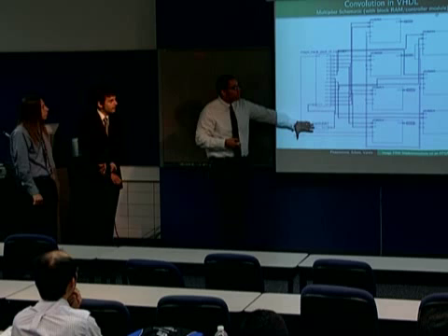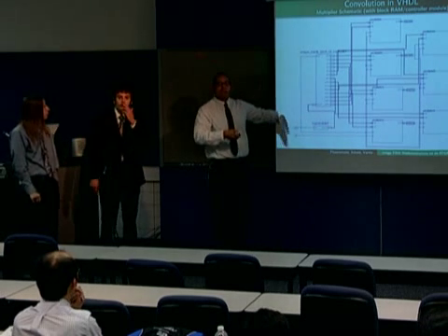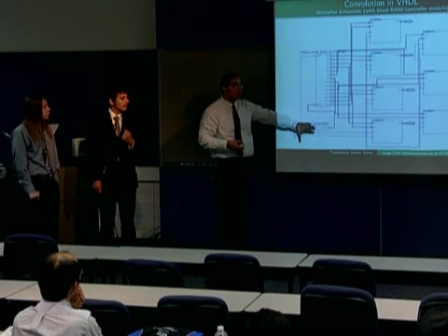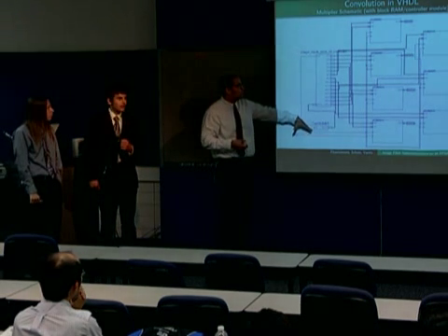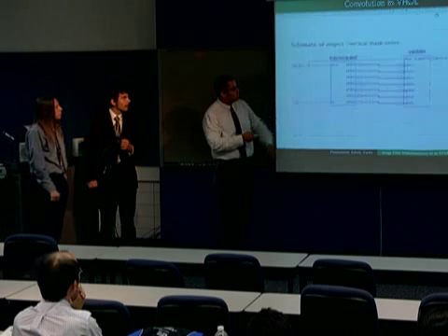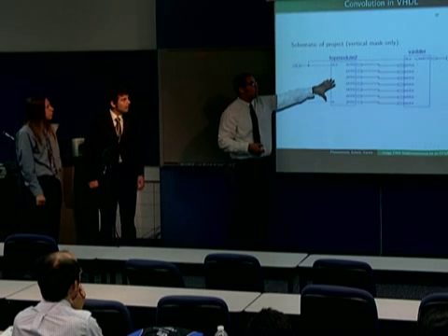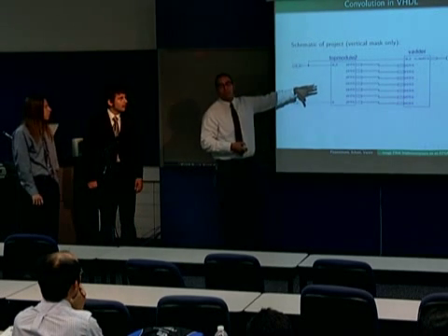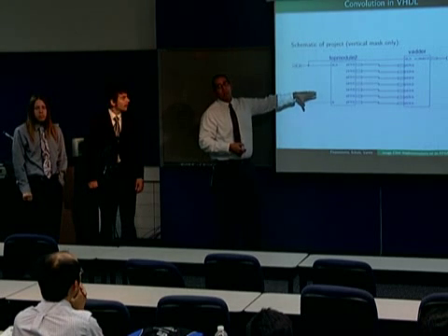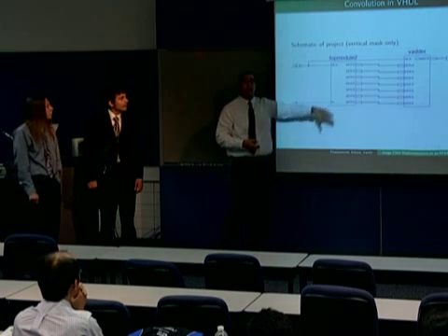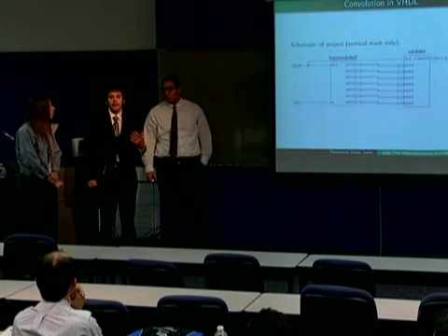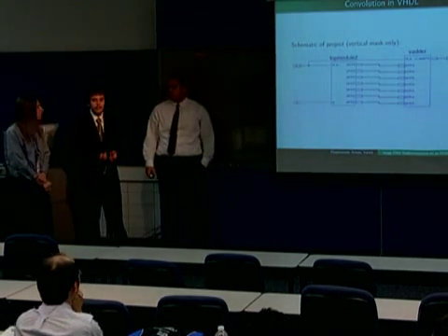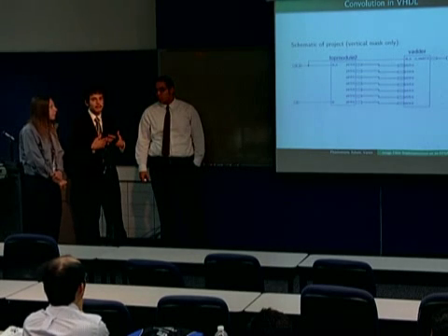This top module here basically builds on top of each other. The top module here is our block RAM with our image and controller that outputs the image values, and it goes into this, the multipliers. Here, this top module 2 is comprised of what you saw on the previous slide. Everything in the previous slides is in this top module 2, and it sends it to the adder. And also, later in our presentation, we have flow diagrams of how this actually works, taken back from schematics.